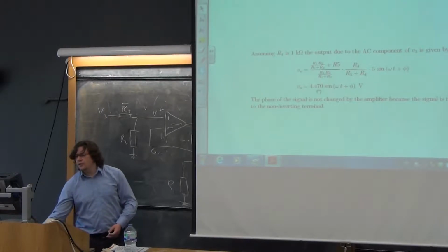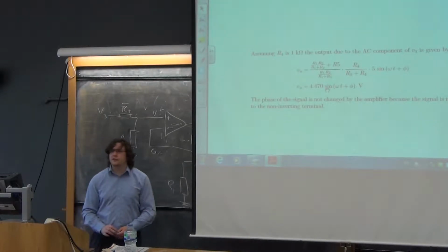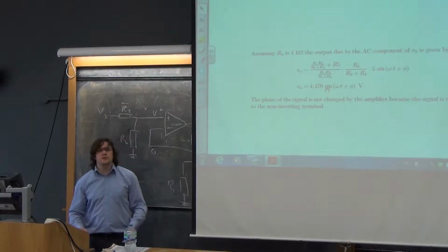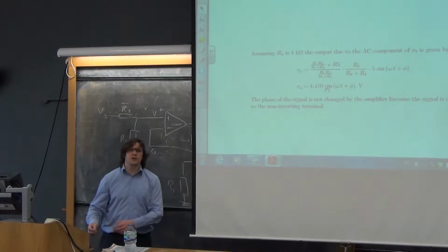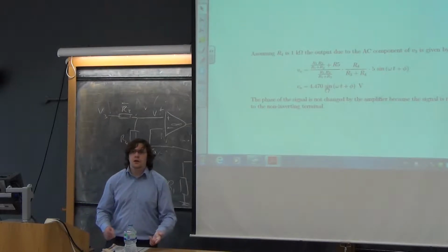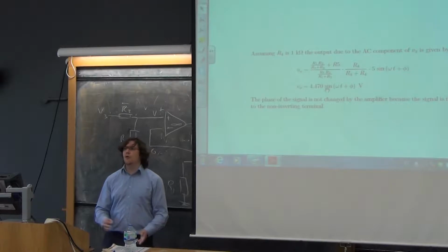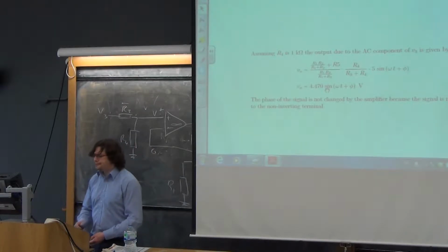And the only other thing it says is, what about the phase shift? Because this is non-inverting, there is no phase shift. So whatever phase it went in with, comes out with. If it was inverting, whatever phase it went in with would come out 180 degrees shifted, or flipped if you prefer. Same thing.